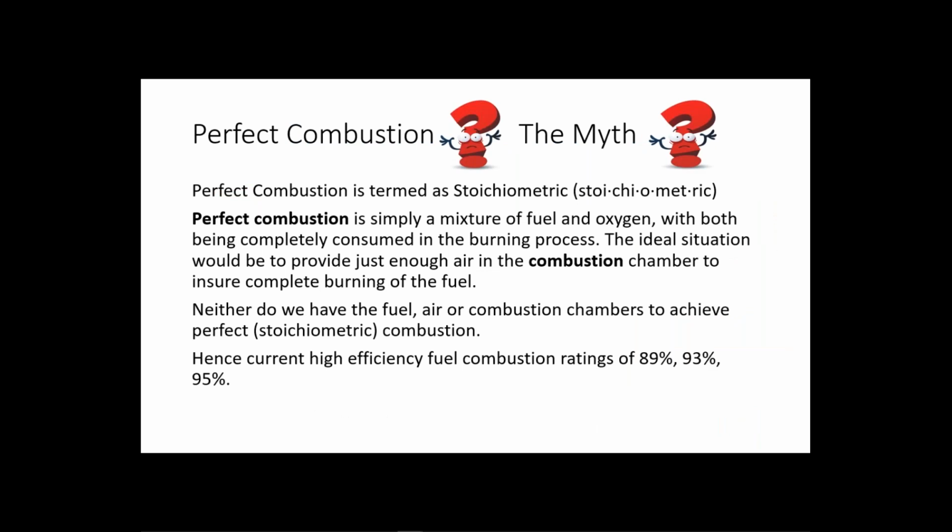Perfect combustion. Is there such a thing as perfect combustion, or is it really a myth? Well, truth is, we haven't achieved perfect combustion in our world yet, and that's due to a lot of factors. Perfect combustion is termed as stoichiometric. Yes, stoichiometric. Perfect combustion is simply a mixture of fuel and oxygen, with both being completely consumed in the burning process. We never do that, and this is why.